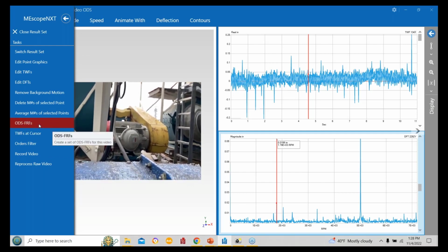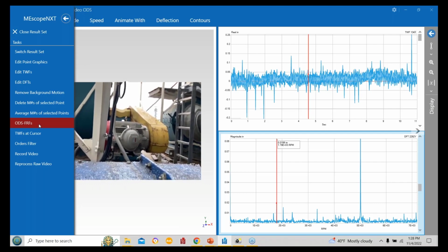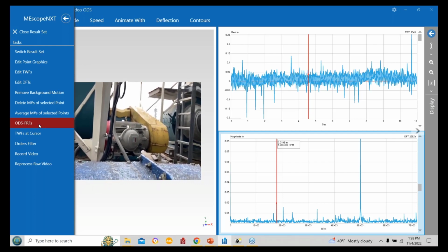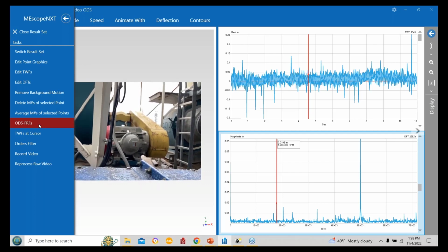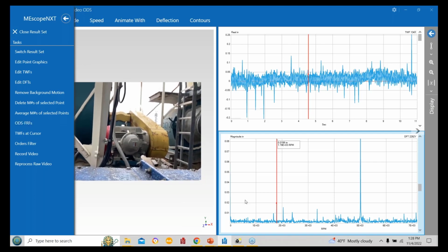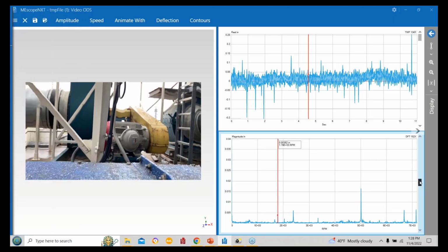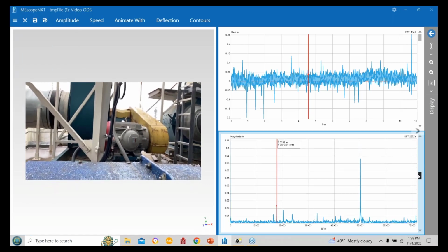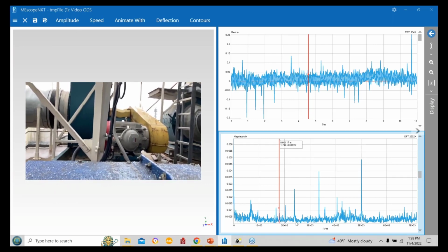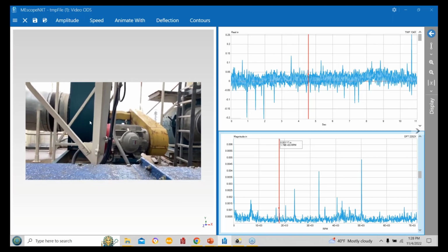We're going to do an ODS-FRF, so I'm going to be able to show you what the processing is. You have a shorter data block, you have a percentage overlap of data, and in this case we're going to have like 25 averages. So what that's going to do for us is clean up this noise floor, and it looks pretty good here, but there's other plots that are jumpy. It's auto scaling all the time, but we'll get stuff like this, which is not a very good peak, and we'll want to clean it up. And the ODS-FRF does that for us, and it's a really nice application.